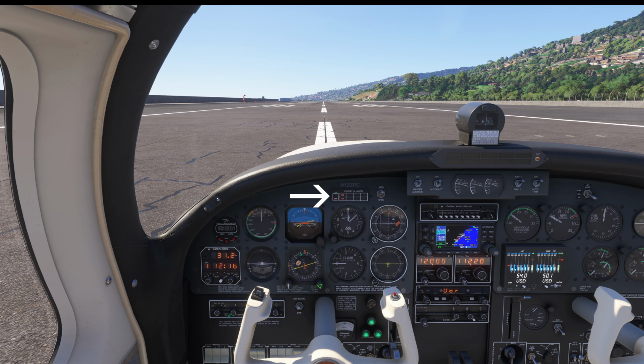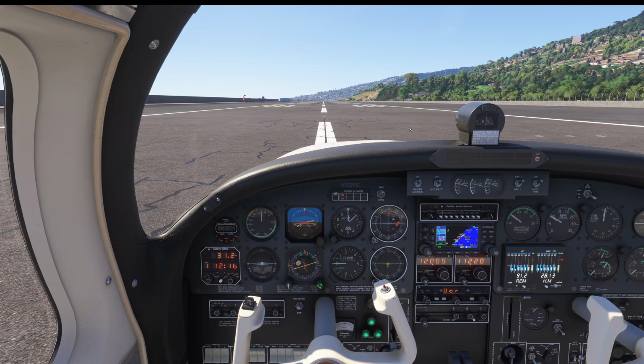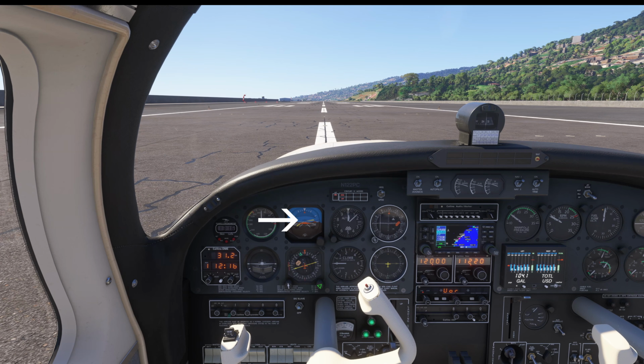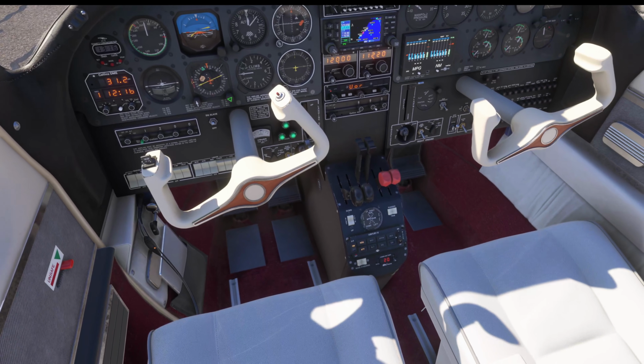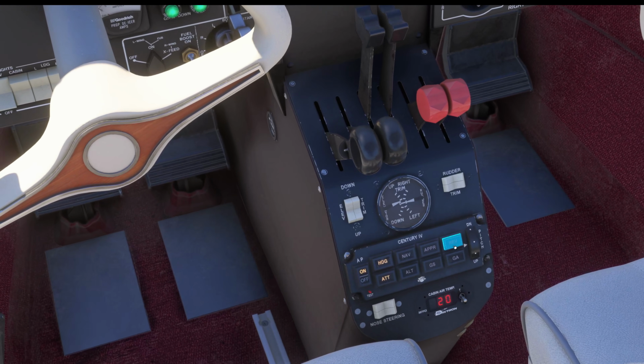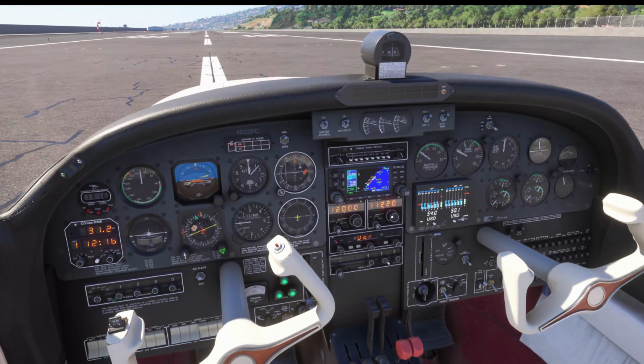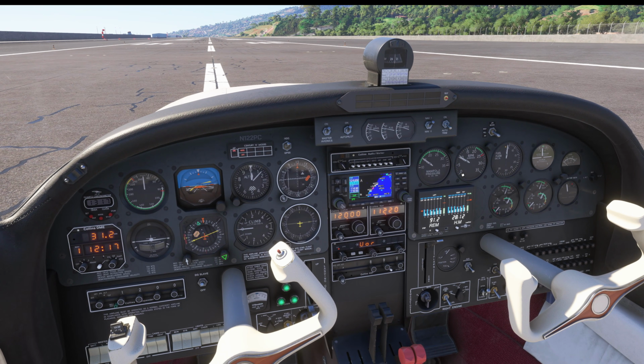So you can see when I engage the autopilot, the yoke begins to move following autopilot commands. If I set the new pitch, the yoke will pull up, and then the pitch trim will slowly follow. This may be a bit hard to notice in the Aerostar, but the trim needle keeps moving up. If I turn off the auto trim, the pitch trim control will be disconnected, but the autopilot will still be able to fly the aircraft, just with reduced effectiveness in pitch.